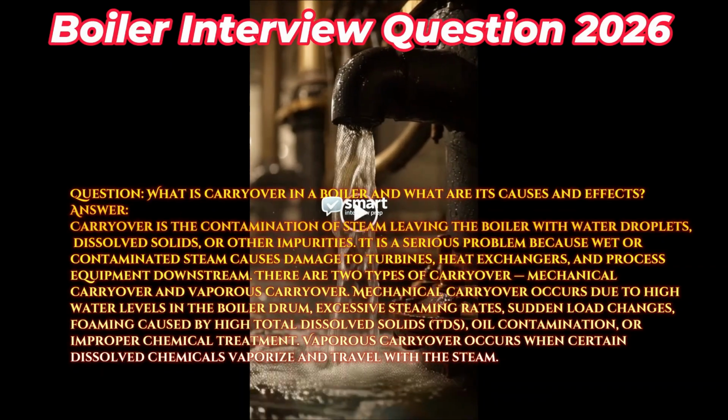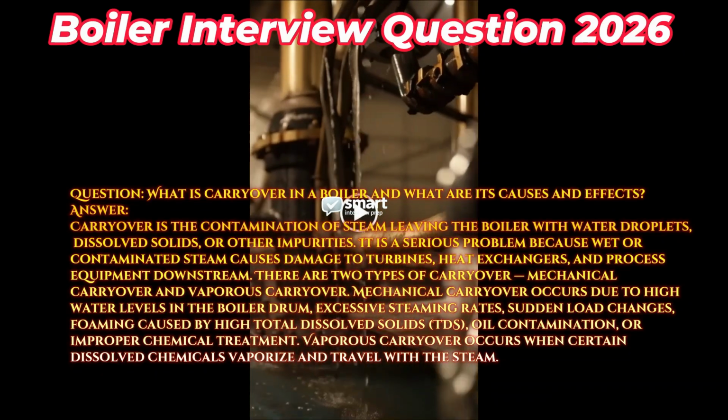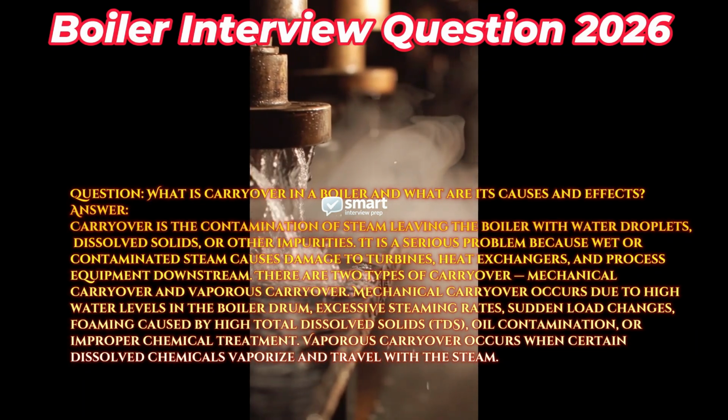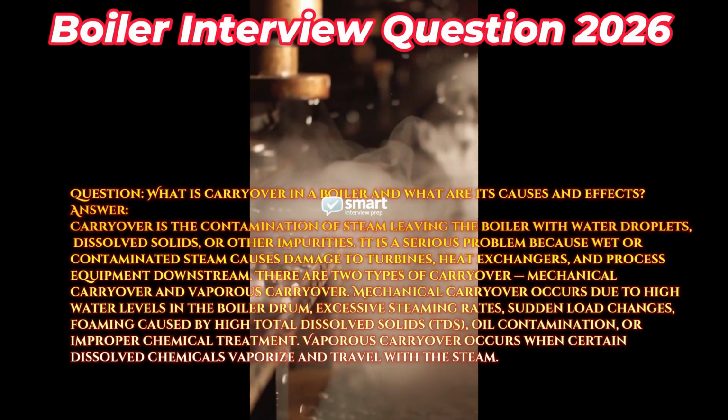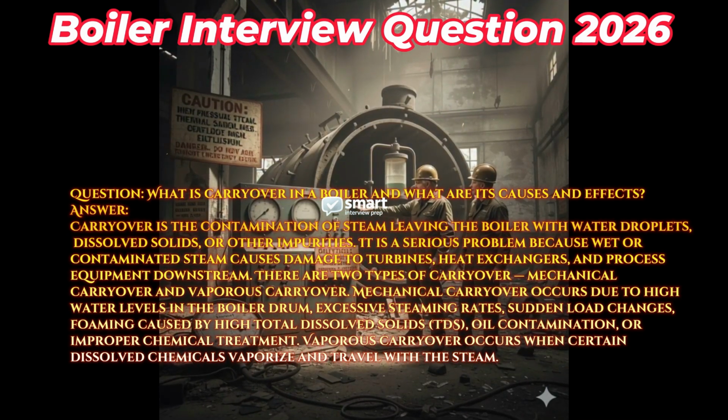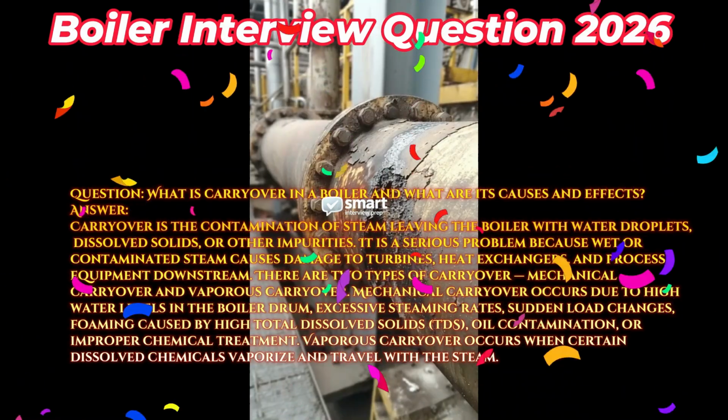Question: what is carryover in a boiler and what are its causes and effects? Answer: carryover is the contamination of steam leaving the boiler with water droplets, dissolved solids, or other impurities. It is a serious problem because wet or contaminated steam causes damage to turbines, heat exchangers, and process equipment downstream.